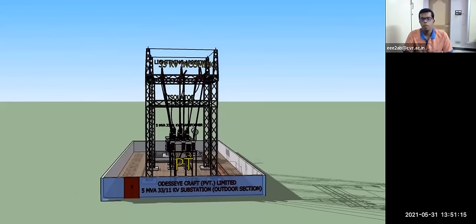And also the potential transformer. The voltage in the line will be 33 kilovolt, 66 kilovolt, or 110 kilovolt. So 110 kilovolt we can't directly measure. In our houses we can measure directly at the plug point. If you take a multimeter, you can measure 230 volts or 5, 10, 15 amperes easily. But for that voltage you would have to design a special multimeter that is very, very costly, and the winding you have to make is very big.